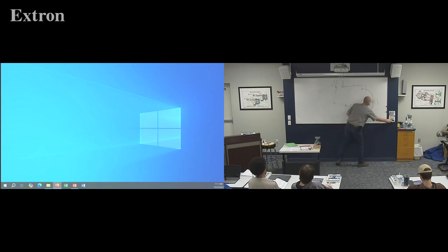So the assumption is if this was the, let's say, deploy out terminal, we just want you to realize following the wiring diagram, if I put the wiring into our lamp box on deploy out, don't worry about what magic happens inside. And if you have power at that terminal and it's not deploying out, you'd say, okay, it's a bad lamp assembly, send it in for repair. That's kind of what we're going with on this lab.